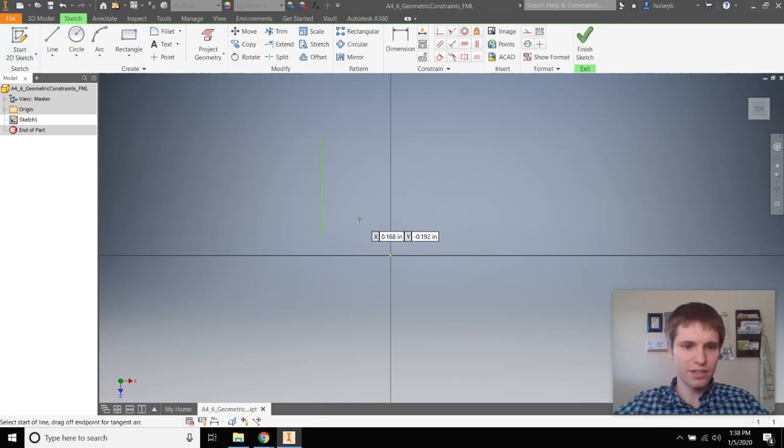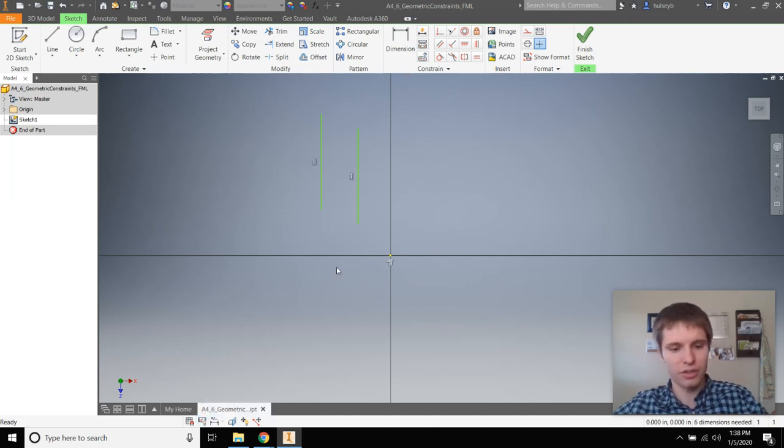Let's do another line. This time I'll show you, you can snap to the up direction, and that constraint is already given to you. I'm not exactly sure what constraints I have, so I like to use this tool right here. This is Show All Constraints. If you're a keyboard whiz, you like F8 instead of clicking down here. F9 is what takes it off.